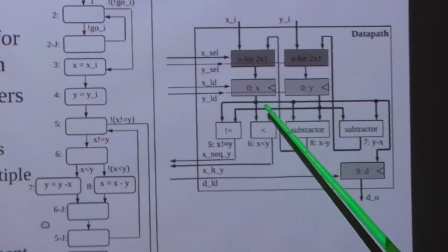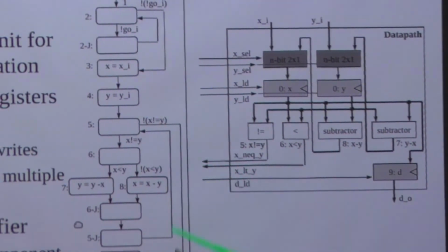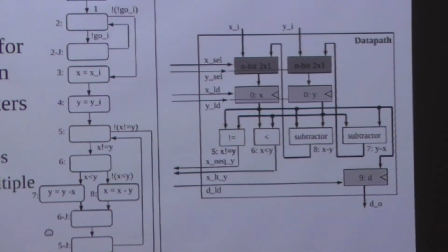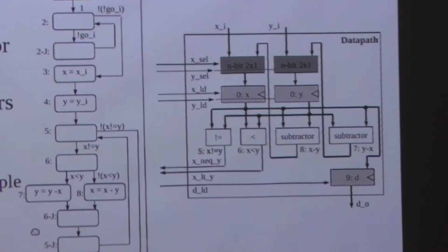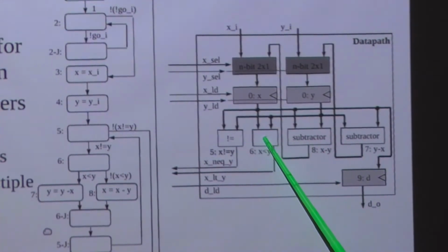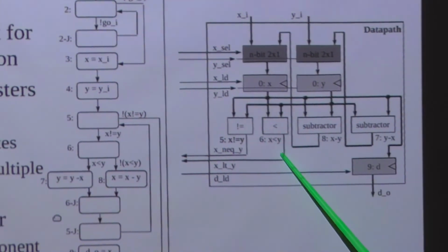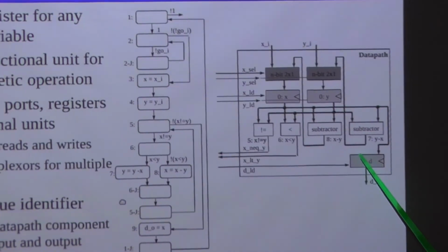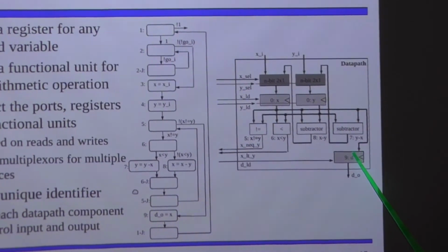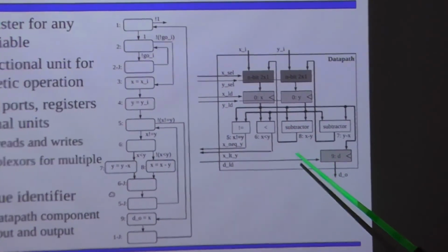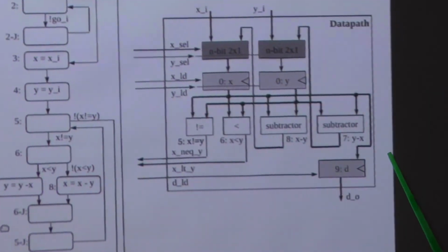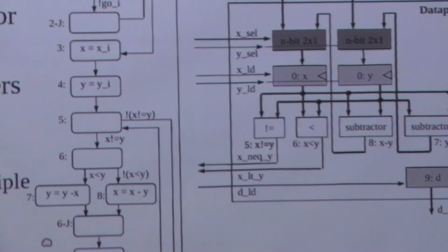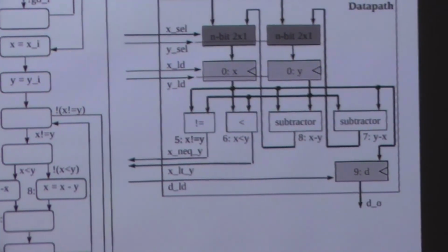And you can see that in every case, the actual operations that are being performed have been hardwired in, right? In the case of this one, we did talk about the comparison unit, and basically this would just be a comparison unit with the less than line fixed and used, and the other lines not used. In addition to that, we also have the D output register, which is being picked from the X line here. It doesn't actually matter. Once you have determined that they're both equal, obviously you can pick either of them and use that as your output, right? Any questions about that so far?